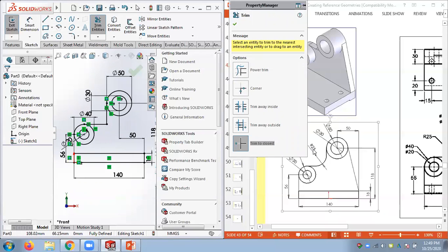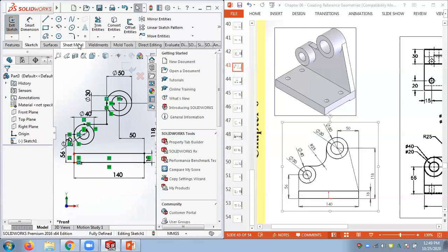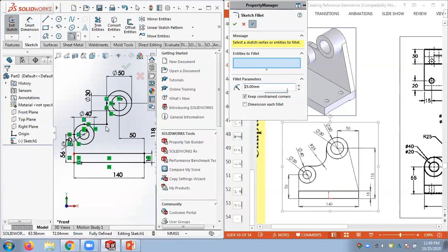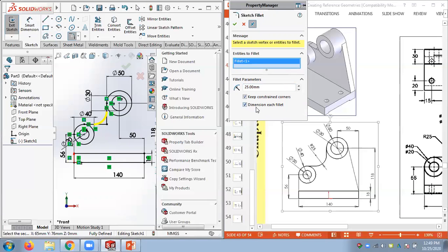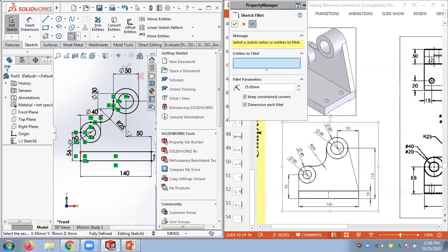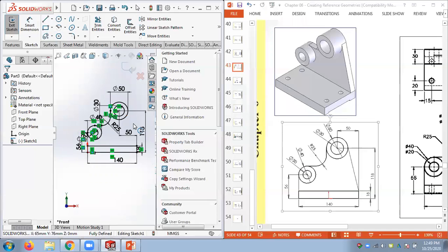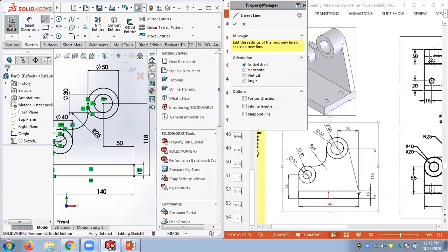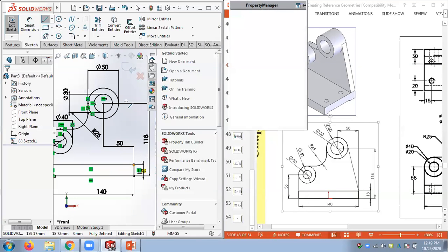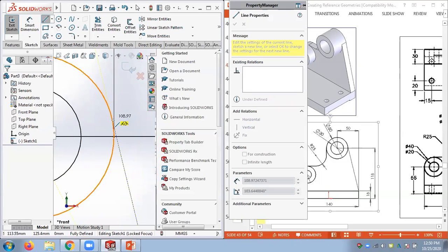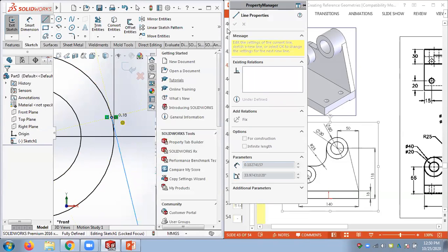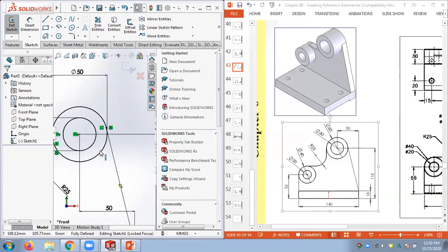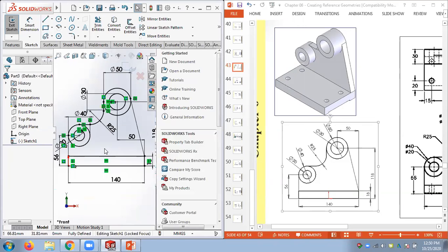Now we have to apply a radius 25 fillet. Radius 25. Select this vertex. Dimension. Okay, that's how it works. I cannot get it from an arc also. If you try to apply the arc tool, this shape will not come because these are lines. Up to here, this is a line, then fillet start, this is a line. So carefully look at the drawing. And this side is from here to here, this is tangent. So I will just apply a tangent relation. The tangent relation appears, you can see that. Okay, so this is how we get the sketch. It's a fully defined sketch.